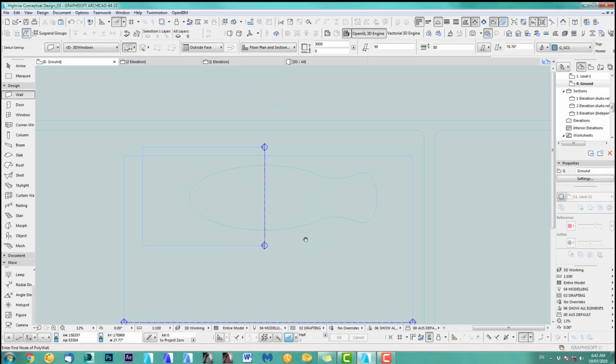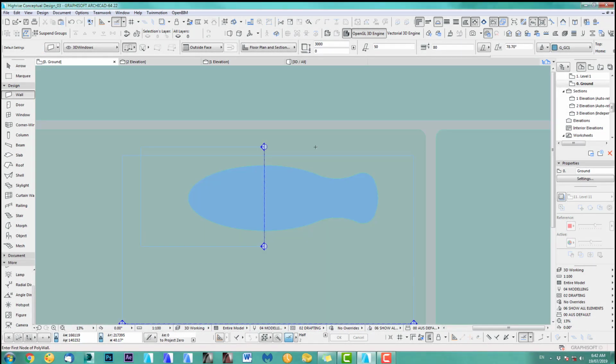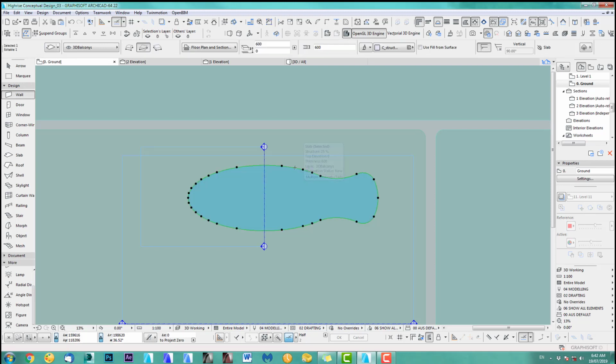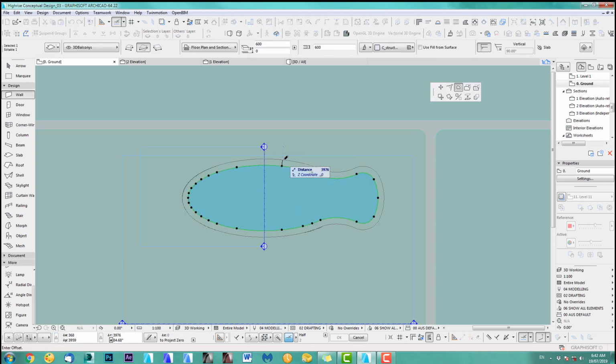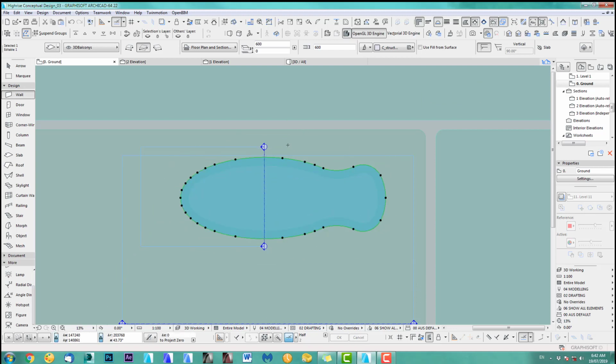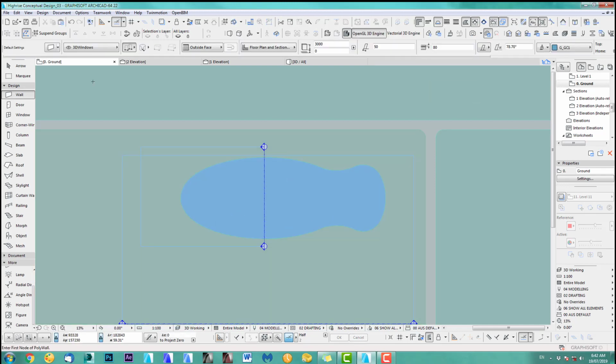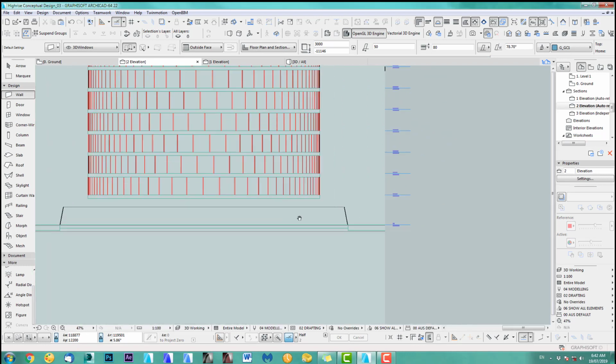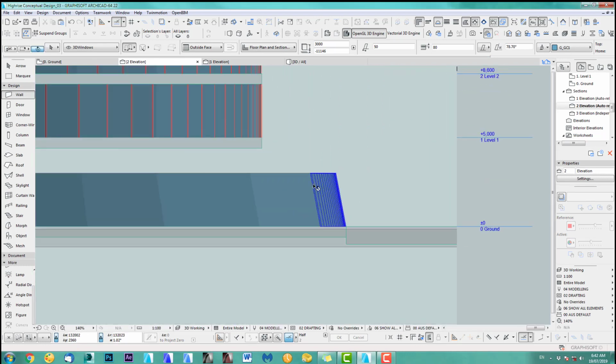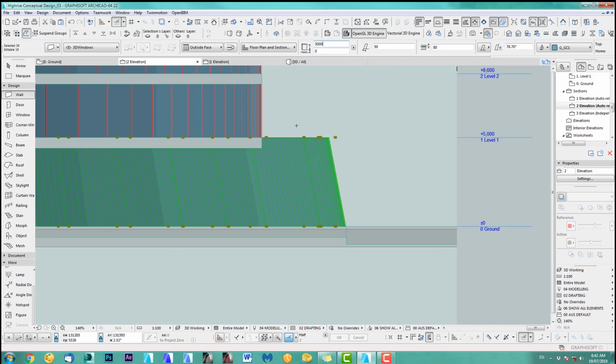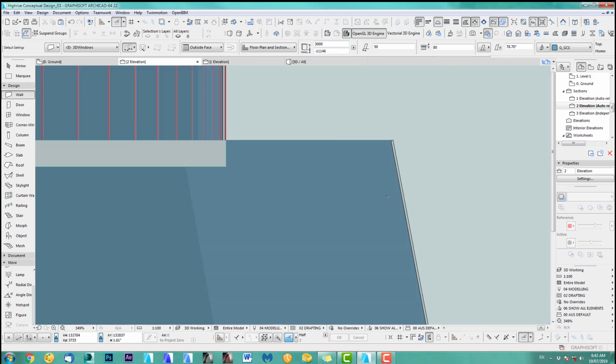Okay, the bottom floor, I just like to make it a little bit wider window and a lot more on an angle. So what we do is we select this and let's move our slab out by 5 meters. There we go, and obviously I have to make sure I move the cut out to my slab. All right, let's take the wall. As always, we have glass, and let's have a look at the elevation. Okay, cool. So we obviously have to make this higher, extend. I got it at the 5 meter level.